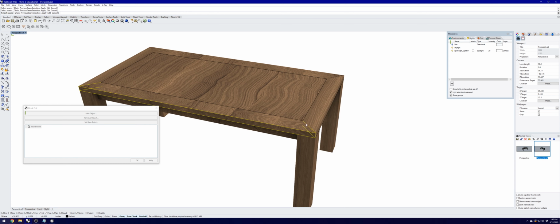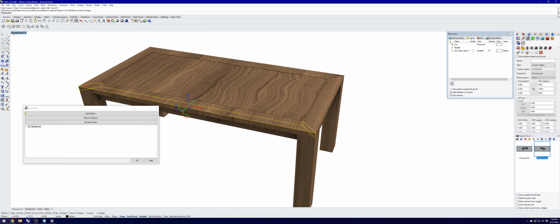The general idea is whatever rail you click on is going to be cut so that when it unwraps your mesh or your geometry, it will create a map of that unwrapped texture that then you can scale up and down. So once I've selected the rails that I want to cut, I'm going to hit enter. And up here it says the UV texture coordinates were successfully unwrapped for selected objects.